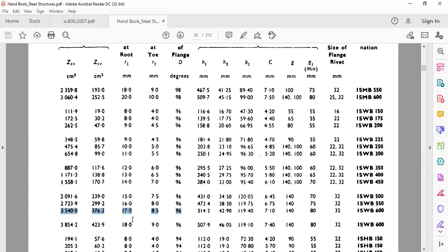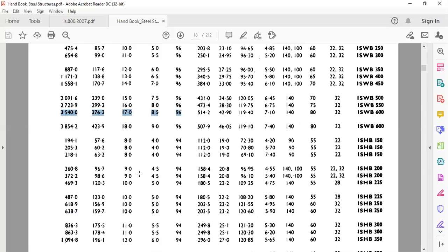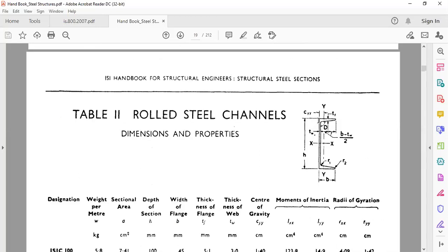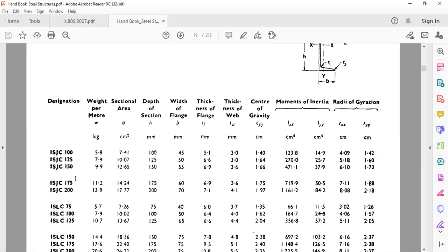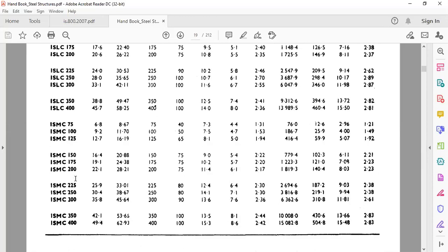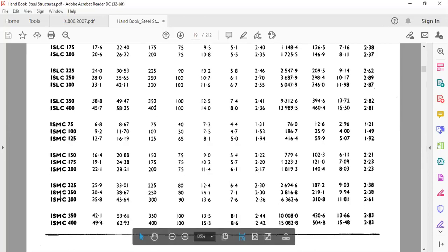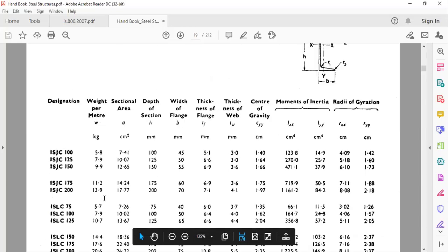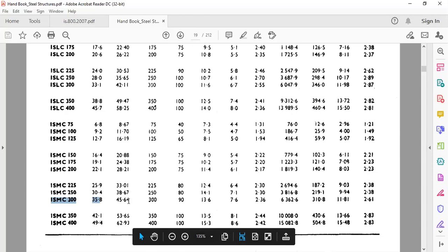So next we have to go for channel section. So here our channel will be available. So with respect to channel, the height is equal to 300 mm. That is our requirement. So that kind of section we have to choose. So it is weight beam, here it is medium channel section we have to choose. Okay, so this section we can choose. So ISMC 300, okay, at 35.8 kg per meter weight. Okay, so that its cross sectional area is 4564 mm squared.